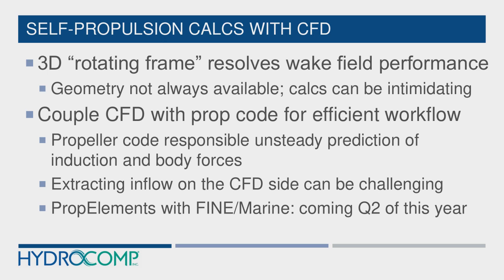So let's talk just briefly about self-propulsion calculation with CFD. CFD is becoming much more accessible, and it's used very frequently for hull form modeling, resistance prediction, and the like. But when it comes to propeller calculations with CFD, we have to put a propeller in what's called a rotating frame model. And of course, that's going to fully resolve all of the wake field performance, unsteady, everything is established there. However, the geometry of the propeller is not always available. We don't know what the design propeller is yet when we're doing our hull propulsor studies.